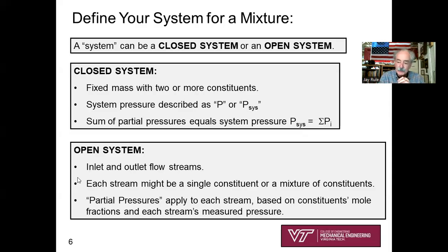You might have an open system, the mixing problem. You might have multiple inlets and one outlet, or you might have a couple of outlets. Each stream might be a single constituent or a mixture of constituents. But recognize that partial pressures apply to each stream based on each stream's system pressure.